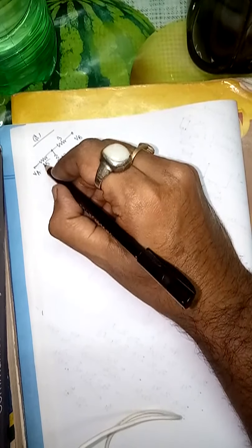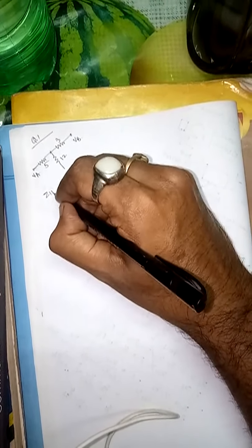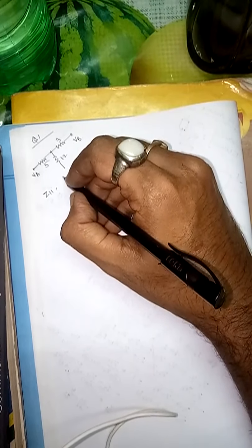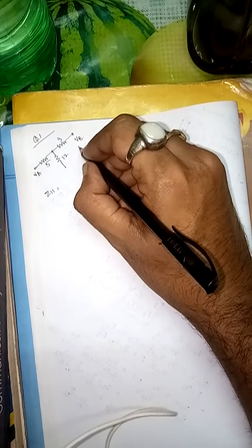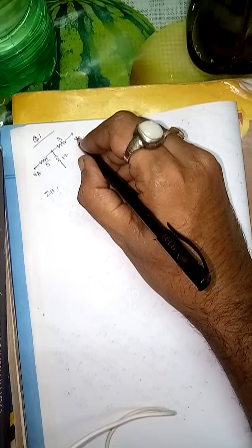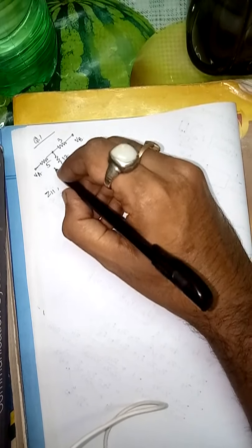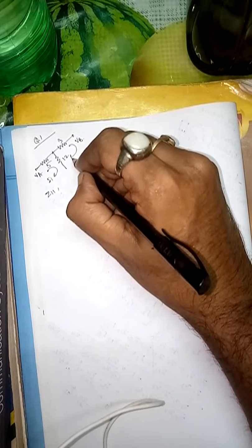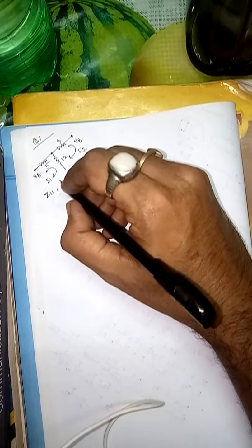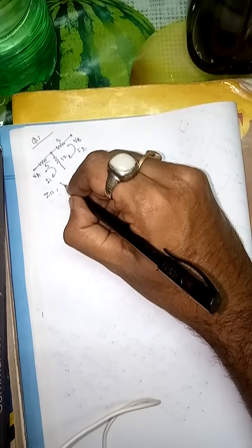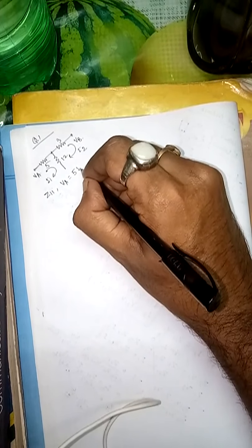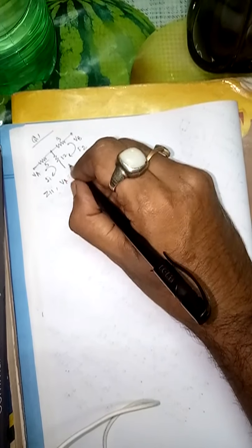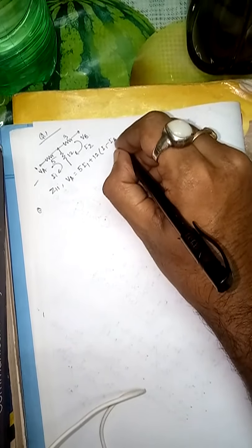So how to do this? First of all, when you are finding Z11, you are putting this condition, actually this branch is not having any sort of current. So if I2 is 0, it means this branch is 0. So obviously what should I write? If this is I1 and if this is I2, so here it is Z11. For that you should write VA equals 5I1 plus 12. Here is I1, it is I2, so it is I1 minus I2.